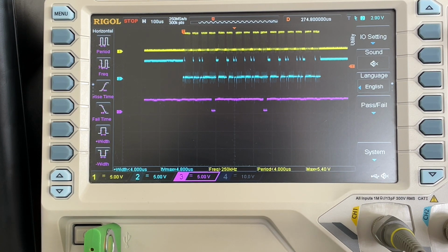The clock signal always comes from the computer. Sometimes it's clocking data that it's sending out, and sometimes it's clocking data that the serial device will send back. So with basically these 3 signals, the one clock signal and a data signal running in each direction, and then, as I said, the other thing that the computer is sending is the chip select, so that the device knows that it's the device being addressed.